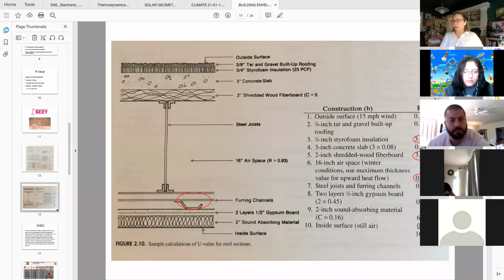We haven't gotten into thermal breaks right now, but what it does is it prevents conductance from the outside to the inside, because there's an air gap in there. So passive house has very thick constructed wall assemblies in order to have a very high performing envelope so that the loads on the building are as low as possible. They have other standards about infiltration and then also ventilation, and there's other factors that they look at too. But one of their biggest ones is very, very high performing walls.